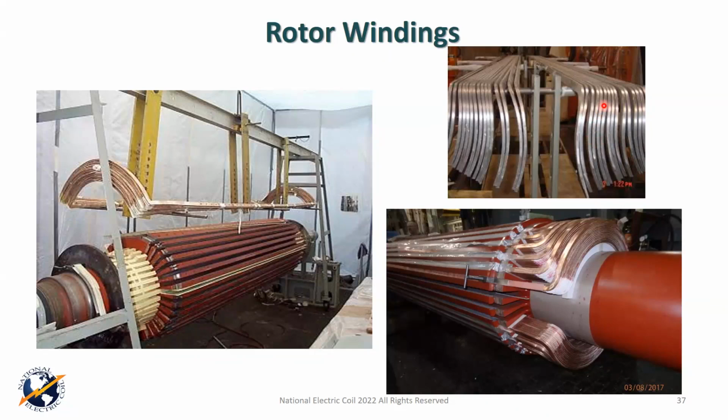It was a tremendous joint until you cycled it. Those things were bulletproof. A lot of those machines were taken by owners who said they were base loaded, or they would just start them up as peakers when needed, but they never had that many cycles added to them. But now we're going to cycle them one, two, three times a day. That joint can't deal with that square corner. It fatigues and it breaks.